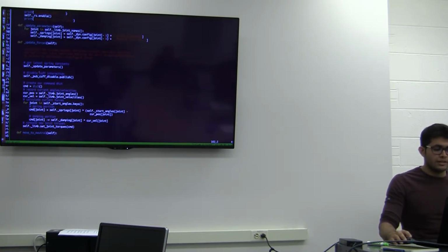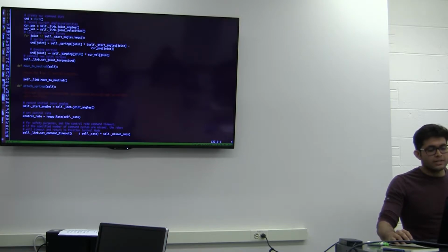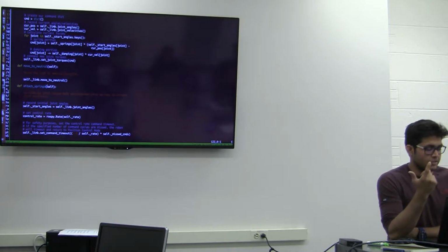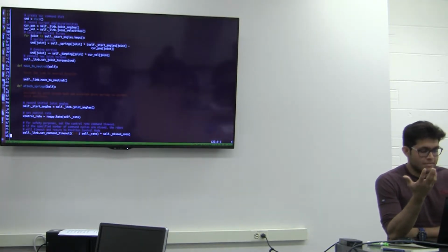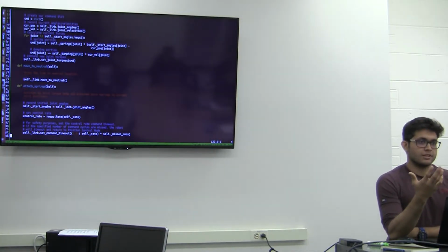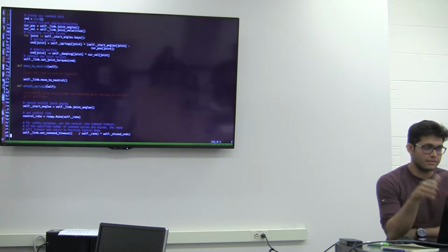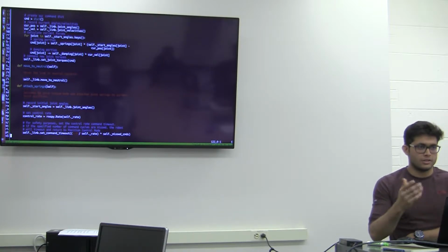So what we are doing here is measuring the current positions and changing it, like calling the dynamic server, so it moves there. Move to neutral, let's talk about this. So what do you think move to neutral is? Service, topic, or message? How will move to neutral function, as a service, as a topic, or as a message? As a service, yeah. So you call this service and it executes the command of moving the Sawyer to the home position as we talked about.